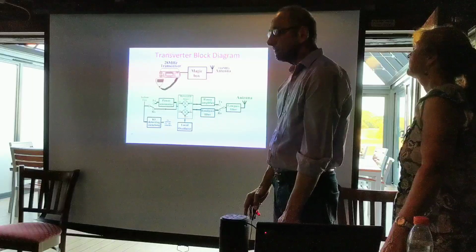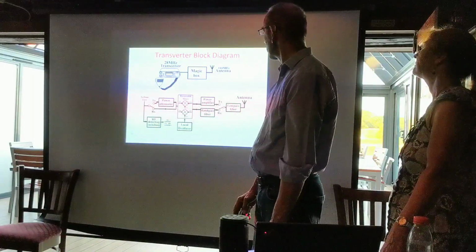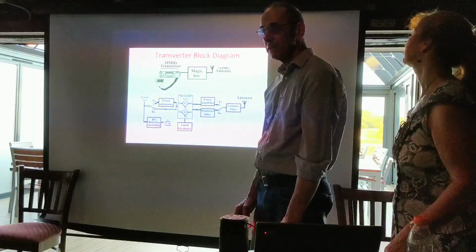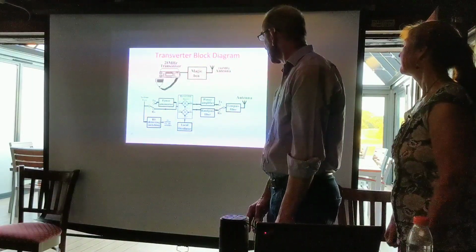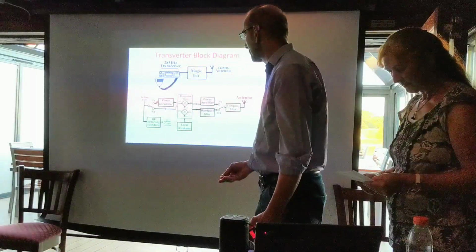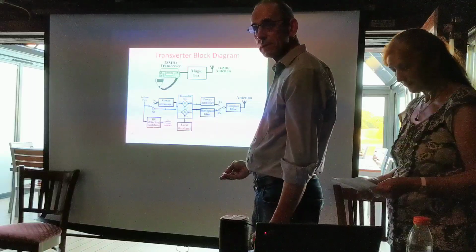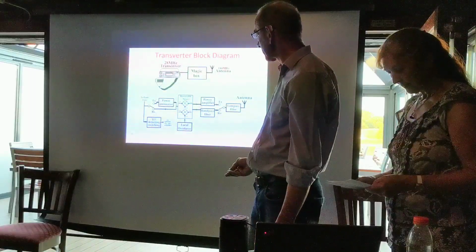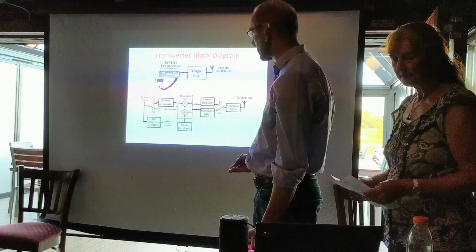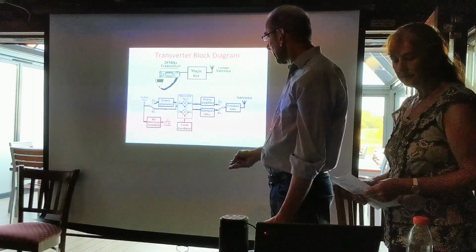So, what's inside the magic box? Well, in this case we've got that same setup, a 144 meg antenna and a 28 megahertz transceiver on the 10 meter band. When we transmit, we need something to detect that we're transmitting, to sense that there's RF there and switch this circuitry over so that it's in transmit mode.